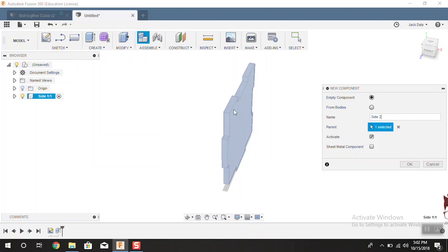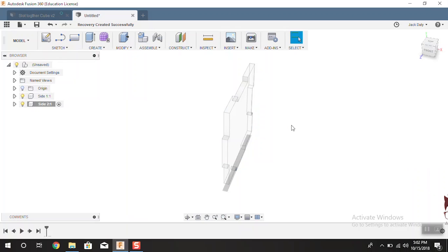Now because we had this as our active component, you see if we highlight that is our active component. You see it's got like that sort of dot in the middle of the circle. So if we then X that out and click on the file, and you can see that that's now selected, and then we want to activate it, because obviously we want to just click OK and start editing, and then click OK, and now you can see that this is now like gone down in opacity, if that makes sense. So we can still see it, but we can't edit it. Now that is key. Now this is actually called top-down design. Now what that means is that you build each panel, if you will, in the same sort of file or assembly, if that makes sense.